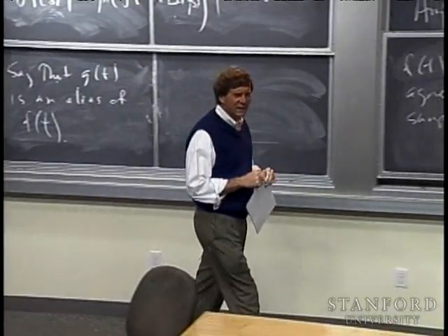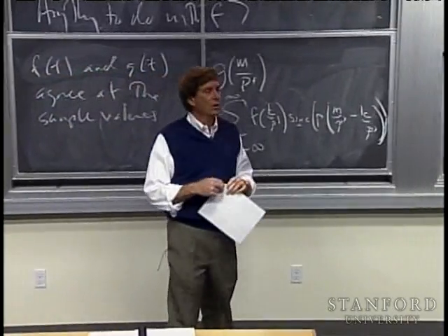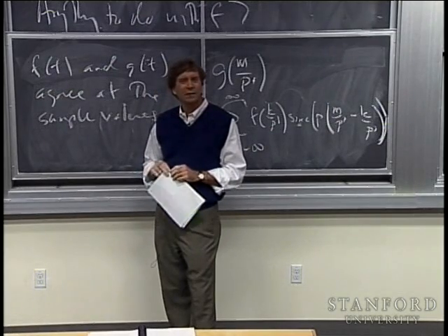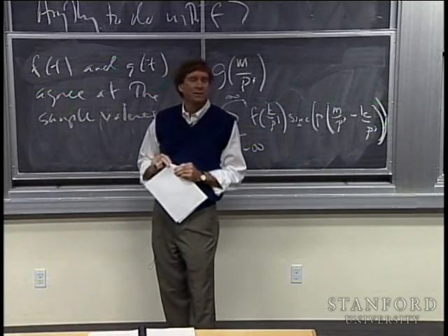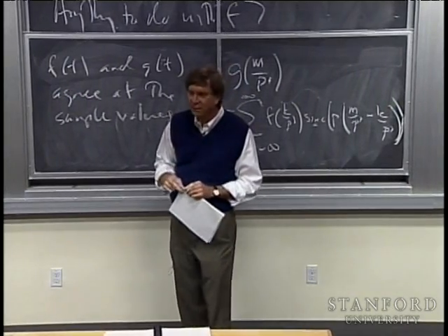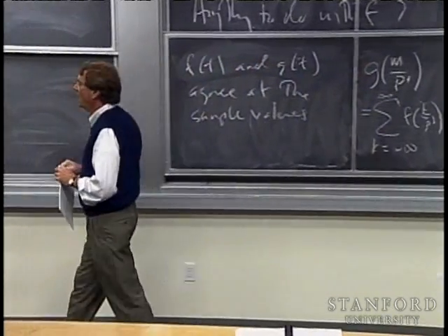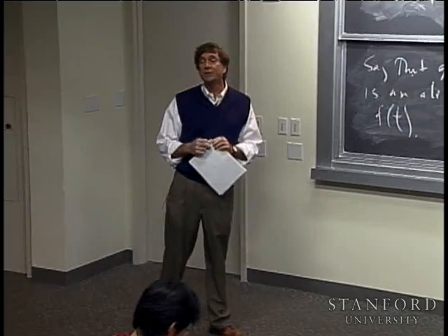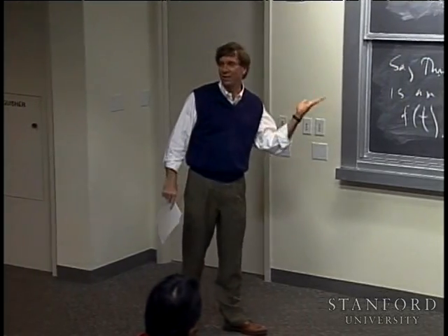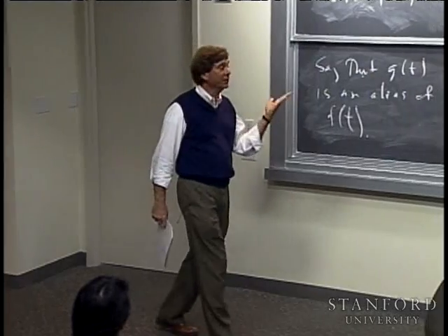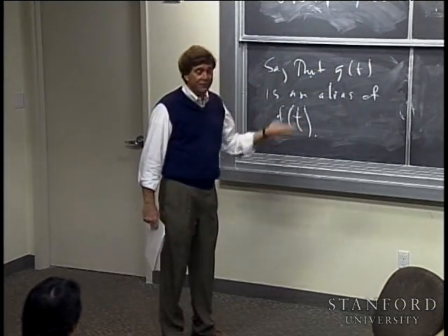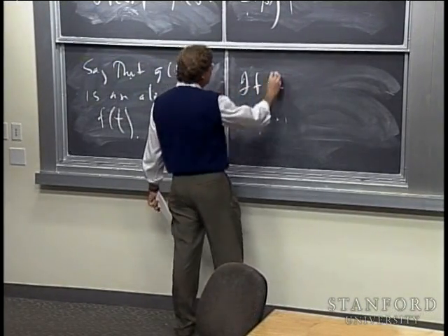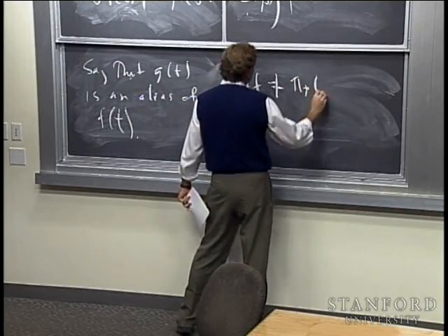Now, you've probably studied aliasing and things like that, and not today, but I hope next time I'll bring in a demo of this. And you may have talked about various things, folding in higher frequencies to lower frequencies and all the rest of that stuff. That's fine. But for me, I never think of the sampling formula without thinking of the derivation of the sampling formula. And if I want to understand what's going on in aliasing, I think about exactly this argument. What's gone wrong? Or what are you doing? The derivation was fine. Everything we did was fine. But what's not true is this fundamental equation. The Fourier transform is not equal to the cutoff of the periodized Fourier transform.